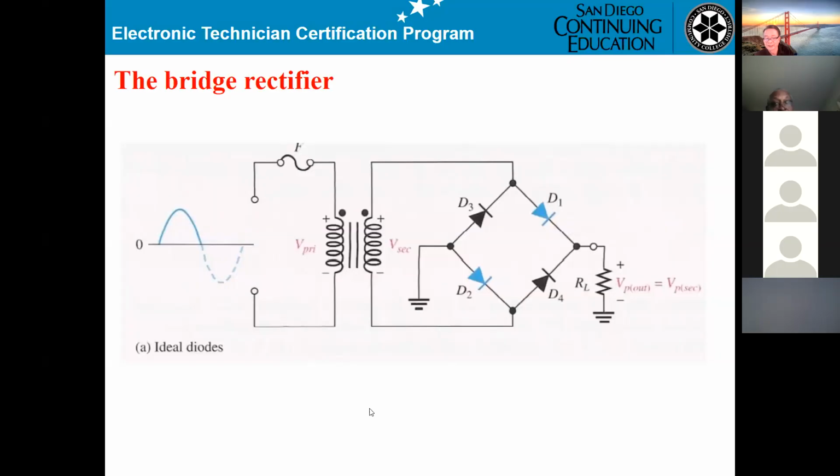Mr. Pham? Yes. When you put the diode value on assignment number 8 and you put 50 volts, is that supposed to be the breakdown voltage? Yeah, that means the limit voltage for the diode. Okay, because I tried it in Falstad and I put it as the breakdown voltage, but I think I did something wrong because it came out 0.5 volts different than PSpice. Yeah, you see the note on that, and that's the assignment. Okay, don't pay attention to that. Okay, thank you.